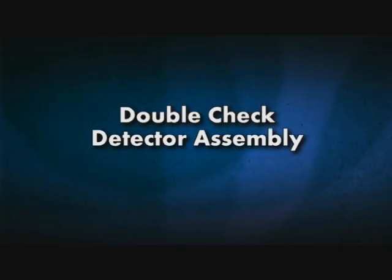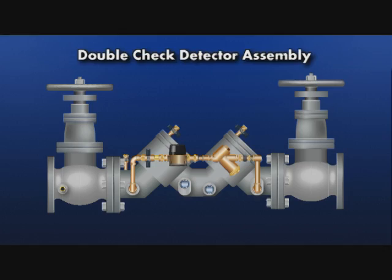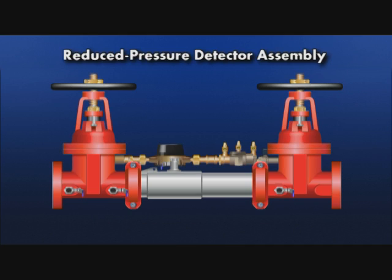A double-check detector assembly, DCDA, is primarily utilized in fire line installations. Its purpose is to protect the potable water supply line from possible contamination or pollution from the fire system. The reduced pressure detector assembly, RPDA, is typically only used on fire line applications. However, this assembly is intended to protect the potable water supply from fire sprinkler systems that contain chemical additives or can be connected to an auxiliary non-potable water source.